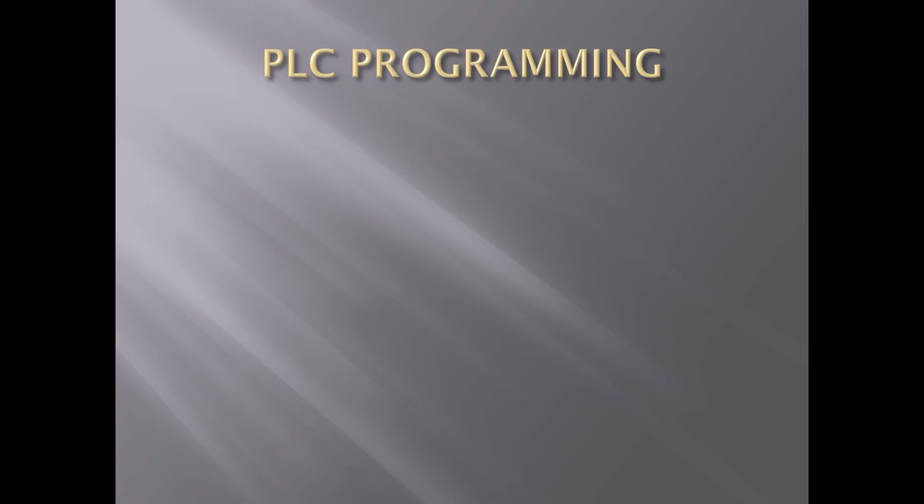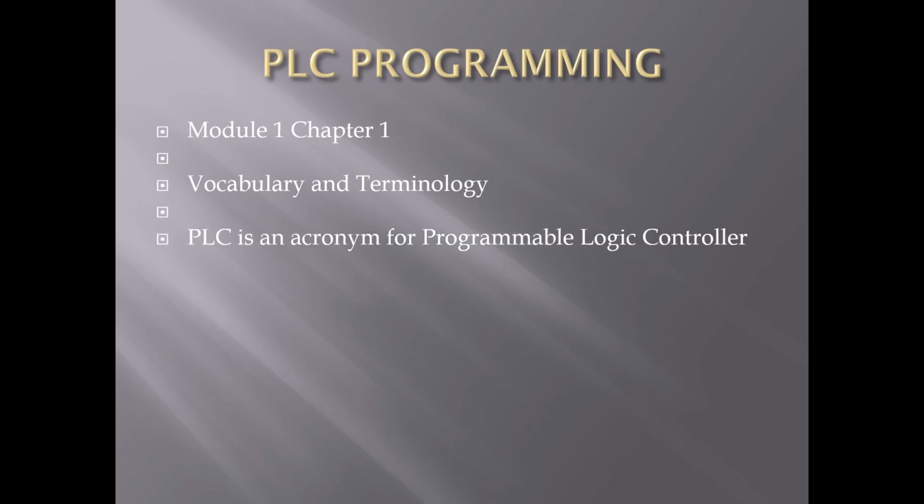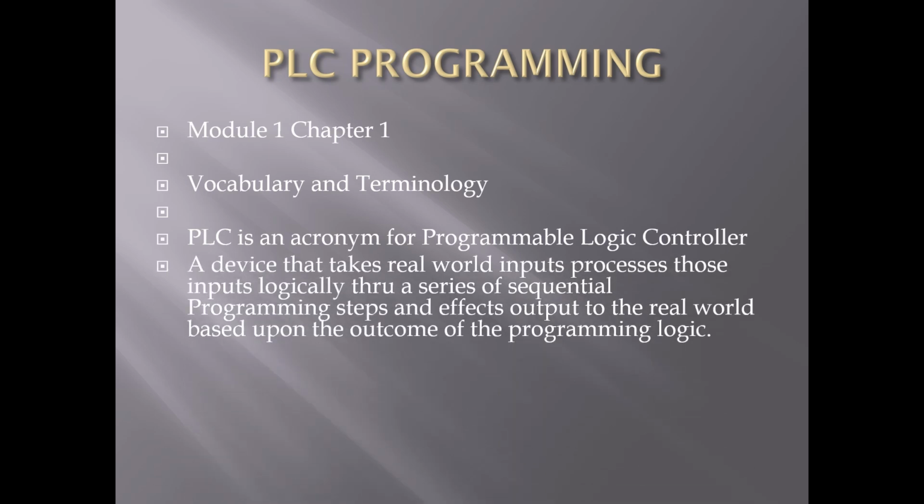PLC Programming, Module 1, Chapter 1. Vocabulary and terminology. PLC is an acronym for Programmable Logic Controller. It's a device that takes real-world inputs, processes those inputs logically through a series of sequential programming steps, and affects output to the real world based upon the outcome of the programming logic.